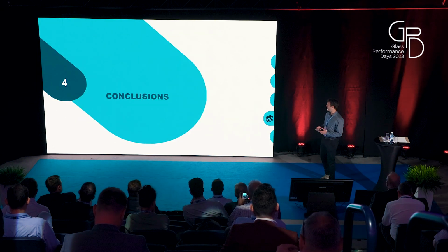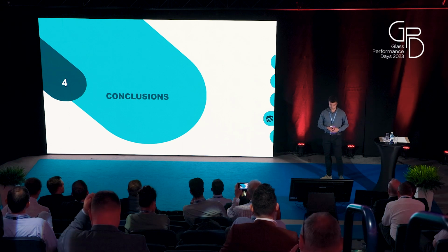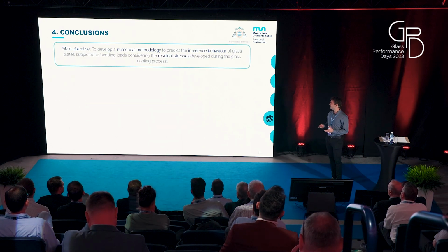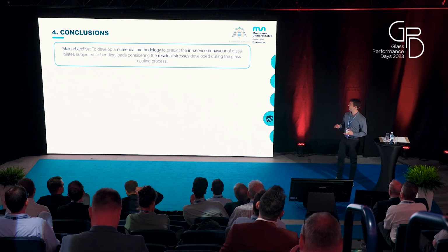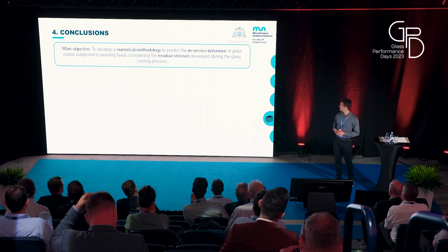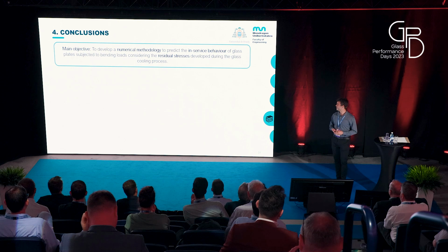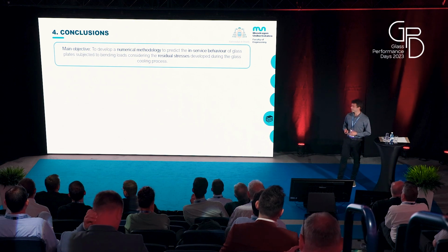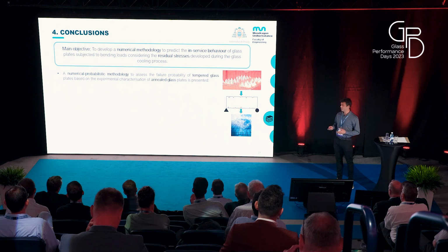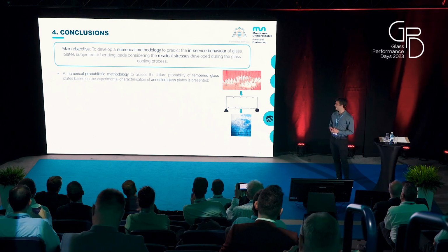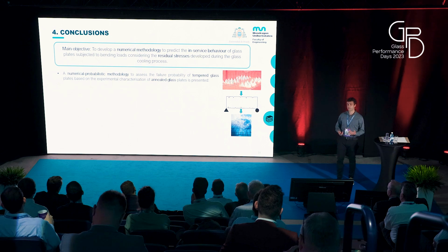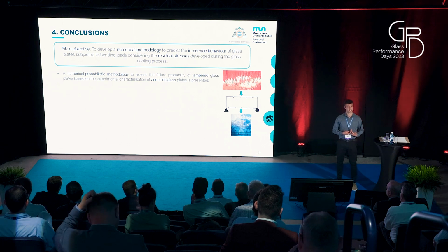So now I would like to draw the main conclusions. So to remember, the main objective was to develop a numerical methodology to predict the in-service behavior of glass plates subjected to bending loads, considering the residual stresses developed during the glass cooling down process. And in this context, we propose a numerical probabilistic methodology to assess the failure probability of tempered glass based on the experimental characterization of annealed glass plates.